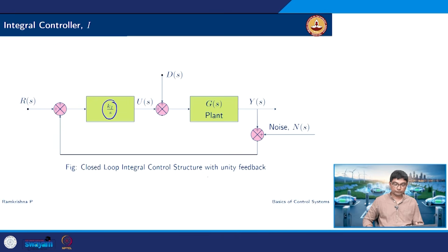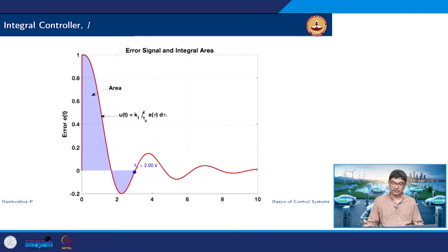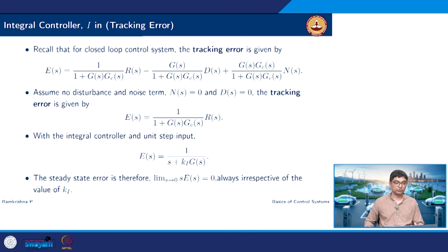Okay. So, what happens in this situation? This is what the integral action does. It remembers the past values, and eventually the error goes to 0. To begin with, we start with an error of 1. The error will keep decreasing as it goes to 0. If I experience an overshoot, it will go in the opposite direction and then slowly damp out to 0.